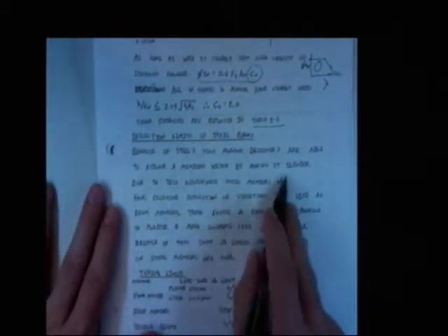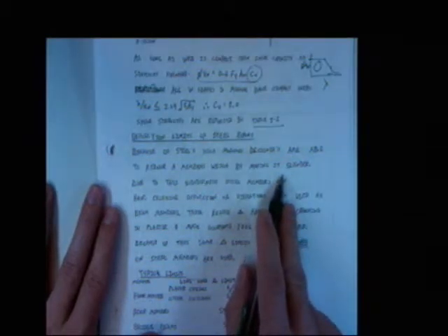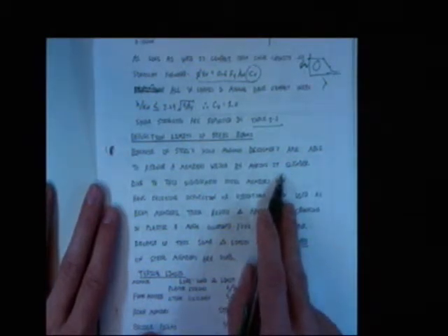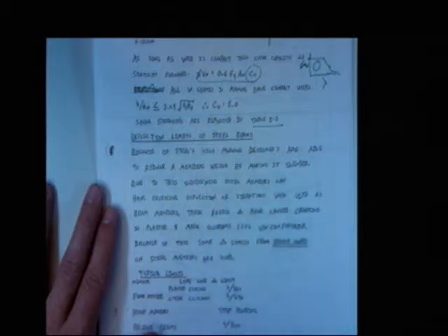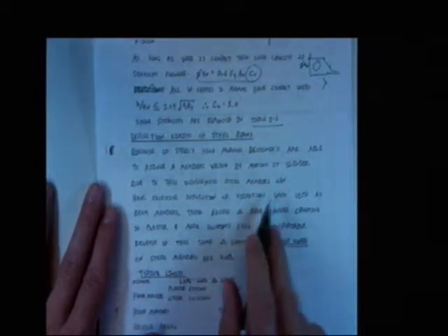Okay, because steel has an extremely high modulus, designers are able to reduce a member's weight by making it slender. That's what the name of the game is. We always ask you to find the lightest section, don't we? Because that's cheapest. Well, in theory, it's cheapest. It's not always. Okay? There's a lot of things that go into cost, about type of construction, how easy it is to construct something, things like that. If you have a different size beam everywhere, oh my gosh, it's like a puzzle putting it together, right? Very hard.